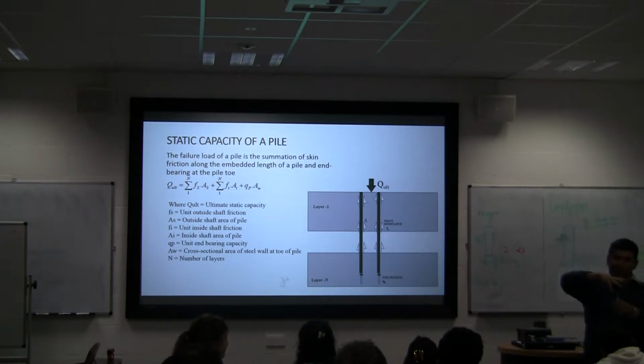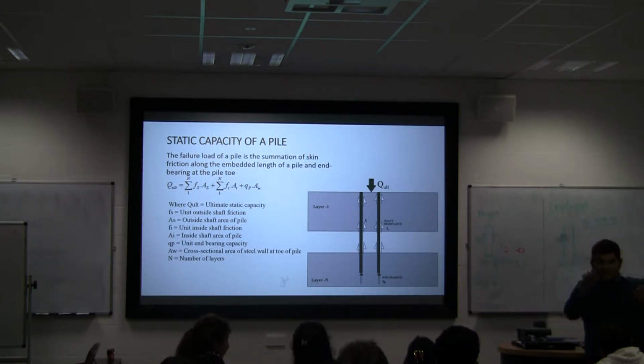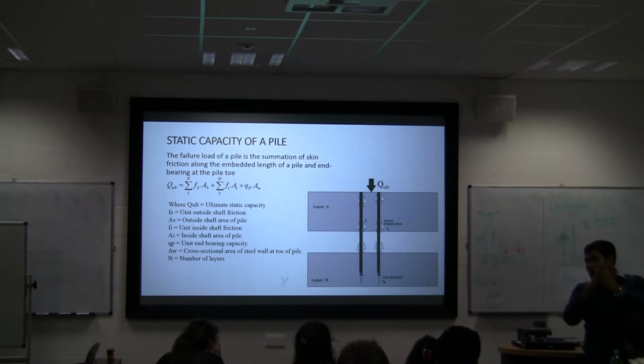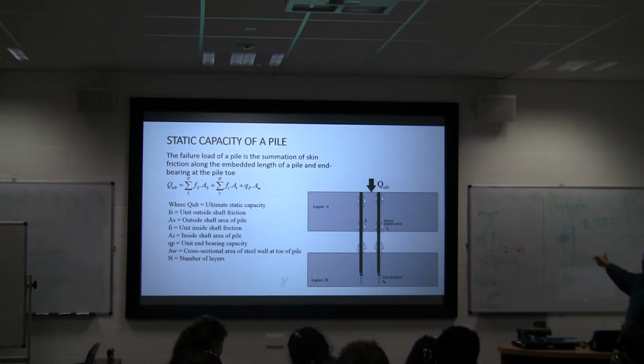You bang the hammer. The stress waves pass through the pile, and that stress wave makes it move down. So that vibration doesn't make it plug, because it makes the soil and the pile move with one another. So the pile completely drives unplugged.